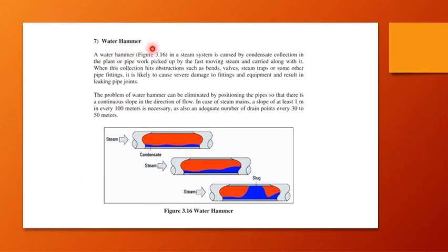Now, water handling is another area of concern when you install any steam trap, friends, and this has to be taken care of. Basically, what's happening here, you can see in the figure. What happens is that the condensate level goes on increasing, and ultimately it will accumulate here in the steam pipe, and ultimately it will lead to steam hammering.